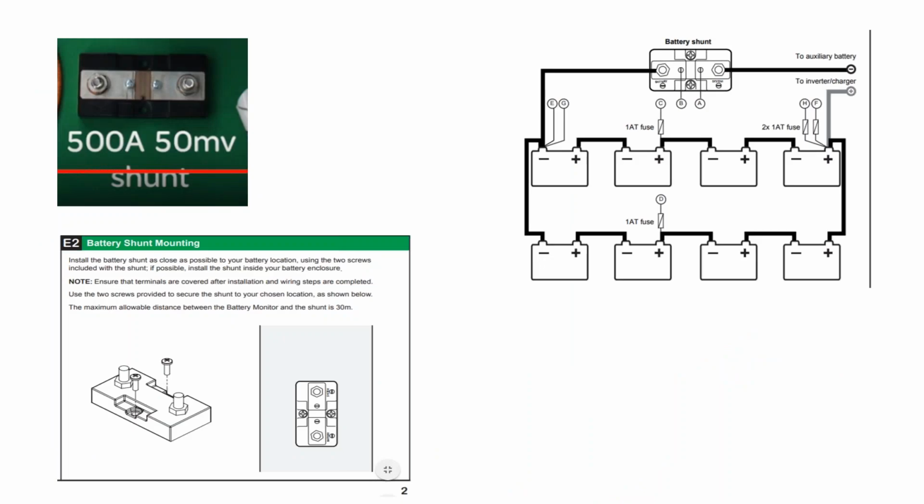So I'm going to show you an issue that we actually ran into in the field this week, getting our off-grid array ready for commissioning. There's an additional component called a shunt. What the shunt does is it measures the current flowing out of the battery bank system. That'll enable you to turn off the battery if it's overheating. It'll enable you to enable load dumping or load shedding. It'll allow you to enable demand management.